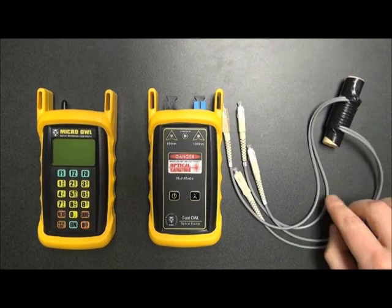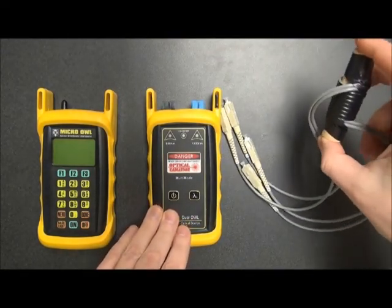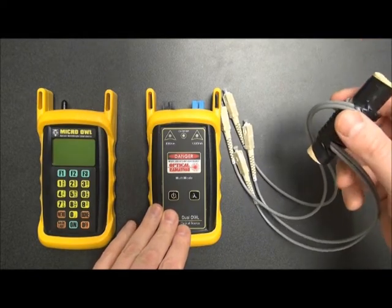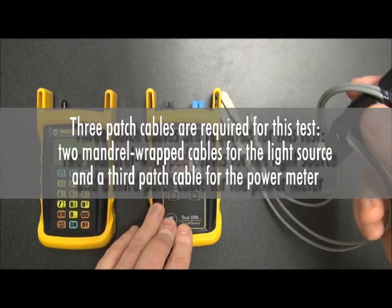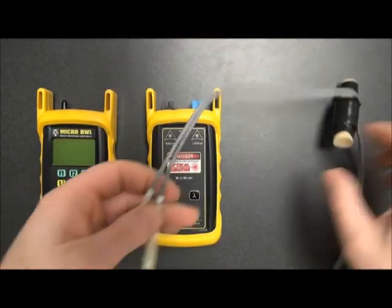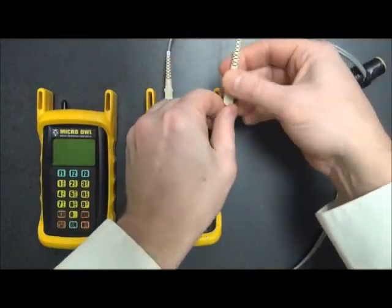So what we need to do first, in this case, we're going to be testing at 2 wavelengths. That's why I have a duplex cable wrapped around a mandrel here. Now, the reason there is a duplex cable is that instead of having 2 mandrels and 2 reference cables, it's easier to manage 1 mandrel with a duplex cable. So what I'm going to do is connect both of our reference cables to our light source ports here quickly.